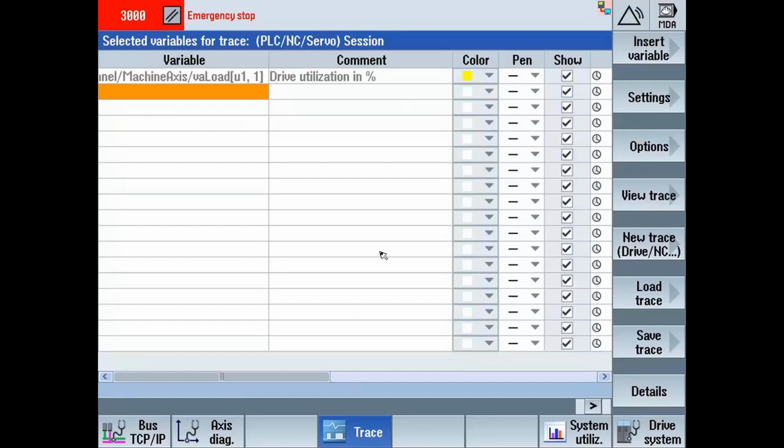And the reason that you would trace drive utilization is, let's say you're looking for, am I being limited by the fact that I'm just running out of juice, being a technical term for the composite of power and current and everything else that a drive can be limited on, and it'll automatically pick up and use the lower limit of the drive value or the motor value. So let's say that you have a motor which has a 1.5 amp capability, the drive has a 3 amp capability. It'll use the 1.5 value instead of the 3 because you're going to be using more of that.